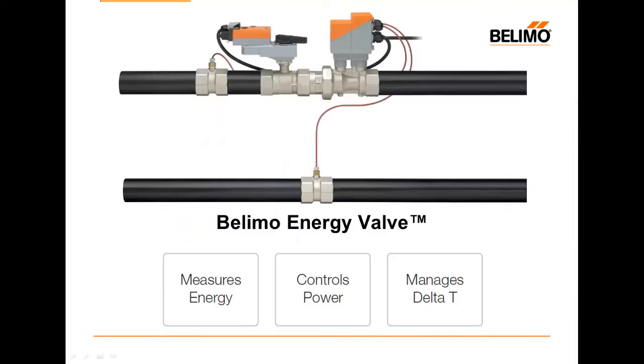Well, let's go ahead and talk about the Belimo energy valve. The Belimo energy valve can do several things. It measures energy, it controls power, and it manages delta T. The Belimo energy valve is a pressure-independent valve with a fully integrated BTU meter.